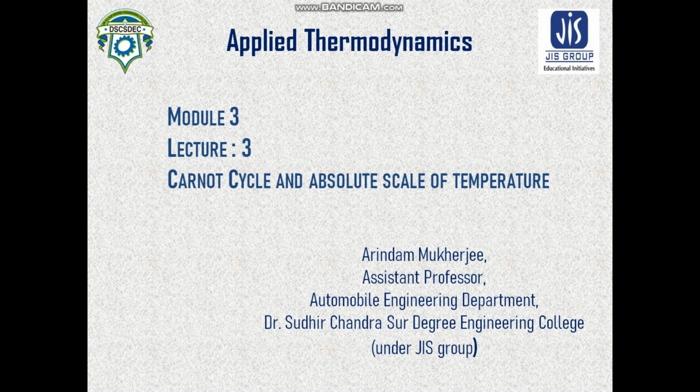maximum efficiency. So reversible processes or reversible engines provide us the sense of the maximum which we can achieve. As you know, according to the Kelvin-Planck statement, there always has to be some amount of heat rejection. It always gives us the sense that the efficiency of a heat engine cannot be 100%. In any case, the efficiency of a heat engine can never be 100%, but still you can identify the maximum efficiency which is achievable.